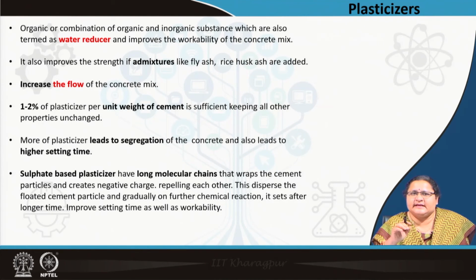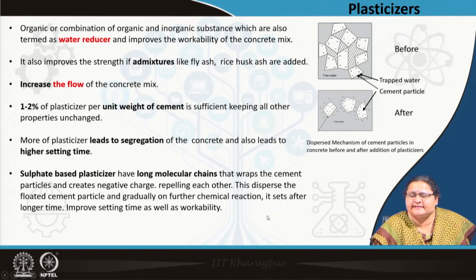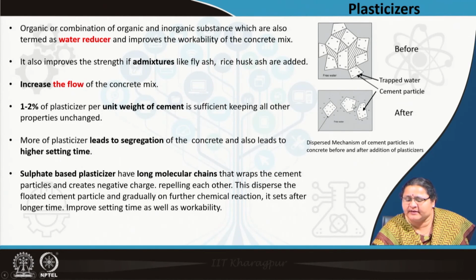Sulfate based plasticizers have long molecular chains. They wrap the cement particles and create a negative charge. You see the two pictures here. Water was trapped between the cement particles here. With the addition of plasticizers, the cement particles are repelling each other and the water is flowing outside, which is helping the other ingredients to move.